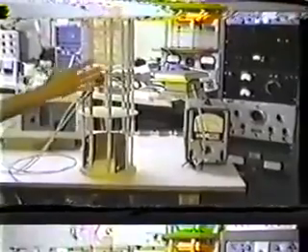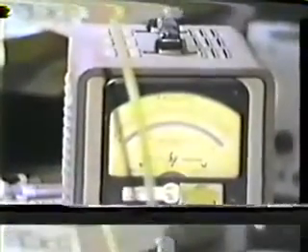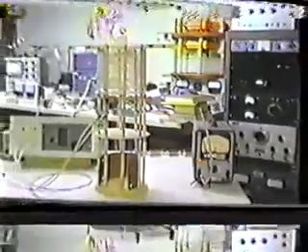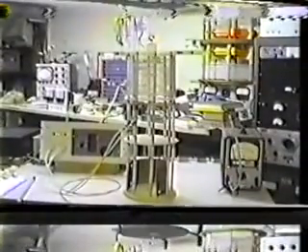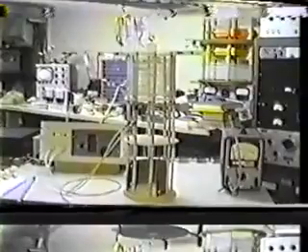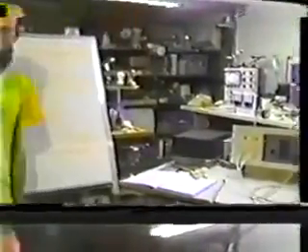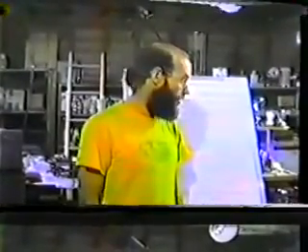And as an example, I'll keep my hand very close to the coil and find the new resonance peak, and it's gone down about 30 kilocycles just by bringing my hand within 3 inches of the coil. And of course, when I bring it away, I have to rehunt for the new resonant frequency. So we'll show you how these waves exist in their analog form, and Tom Brown will give you a brief introduction on the relation between the analog computer and the digital computer, and why we have to use analog computers for the study of these waves. And this will constitute part 2 of this videotape.